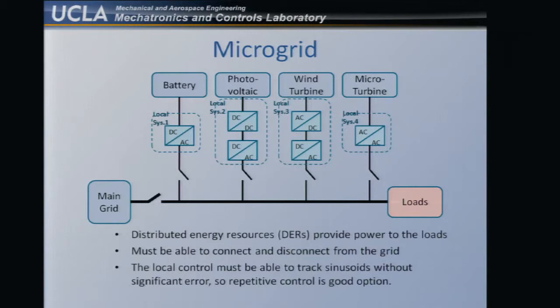This is the kind of architecture we build. We build the models, and this is all simulation work, no hardware. When it comes to hardware, I'll mention that. We build models for microturbine, wind turbine, PV and battery. We also have the model for the power converter, and those converters switch at 100 kilohertz. The control is really the pulse width modulation of those switches.